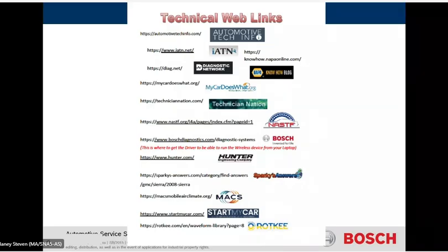And I could tell you a bunch of stories about that. But that is outstanding information there. My next one down that I use on almost a daily basis is the one in the middle, NASTF. If you've never been to that site, you should go there. You would blow your mind the information that's there. That's free. That's also the site that I use if I'm doing any J2534 programming or reprogramming. And then all the rest of them are great.